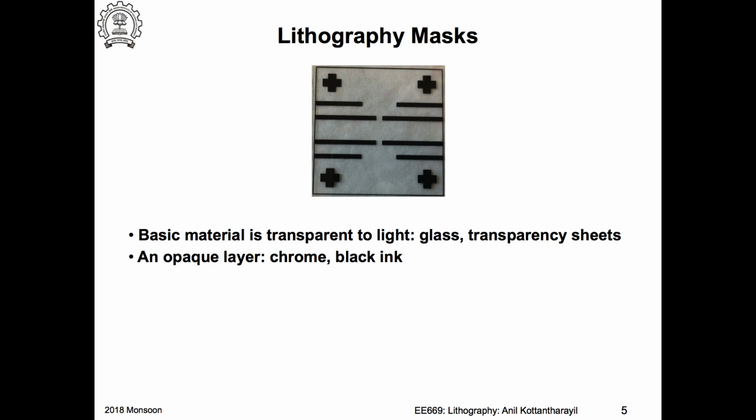Okay, so this mask is very important because for every stage of patterning in an IC, you would have to make a lithography, except for selective epitaxy, if you use it. Every other selective process, where you want to etch something, or do implantation only in select regions of the wafer, you need to precede with a lithography step.